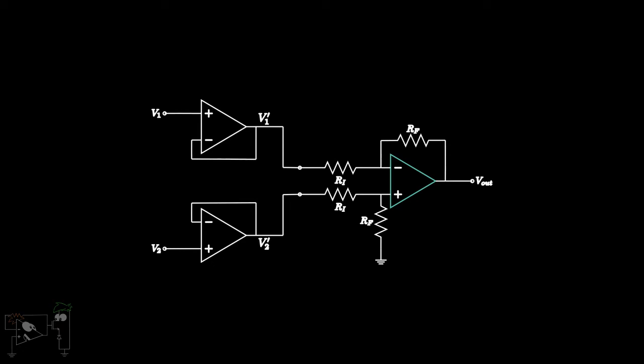This circuit now provides matched, high impedance inputs so that the impedances of the input source will have minimal effect on the circuit's common mode rejection. The 2 op amps on the left now handle the driving of current through the resistors instead of letting the input voltage sources do it. The increased complexity of the circuit is minimal, but the benefits are huge.